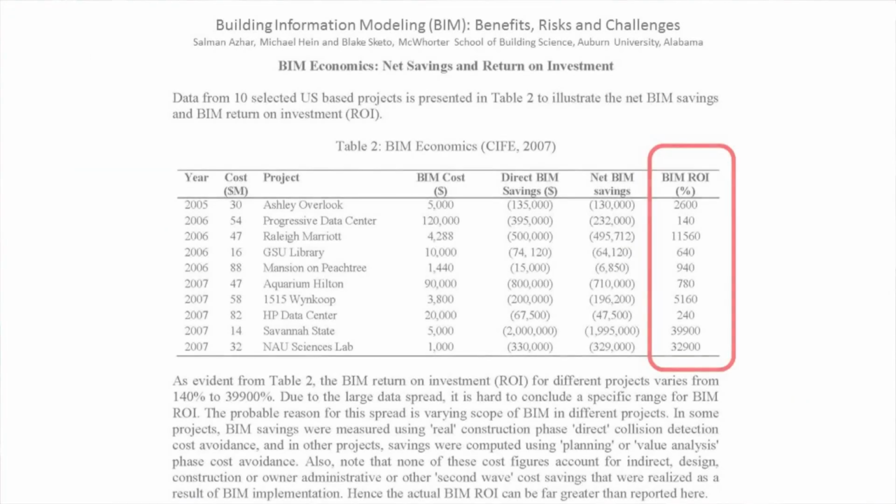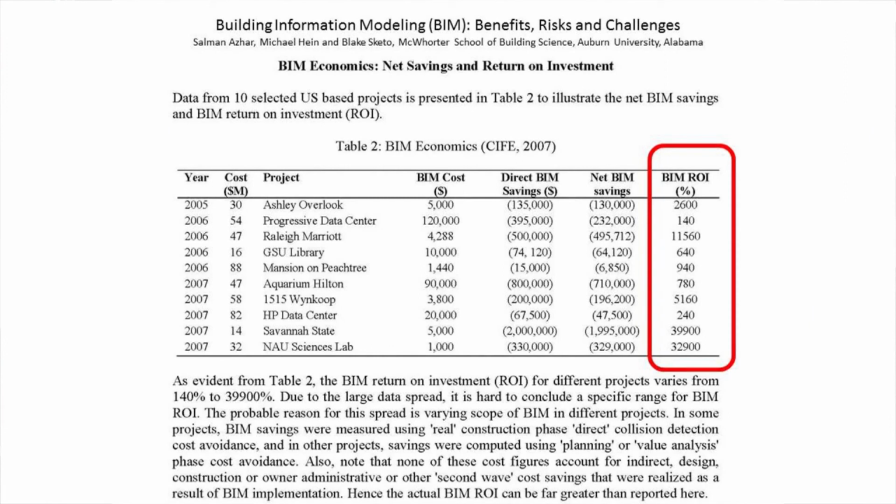Then you can assign the status to active, reviewed, approved. You have to review it with your engineers, with the mechanical, with the structural engineers, whomever is involved in these clashes, get it solved and get it done. And that's really the important part of this clash detection.